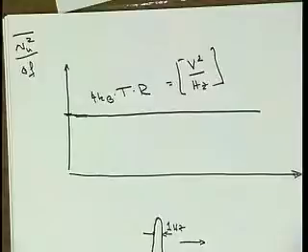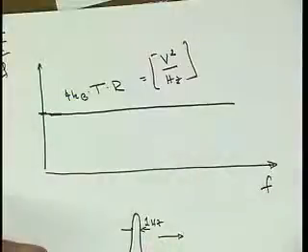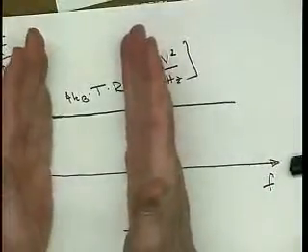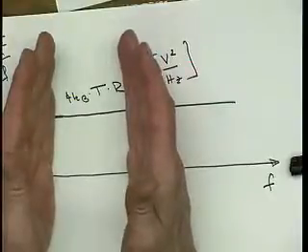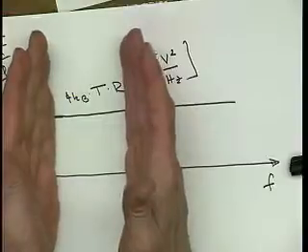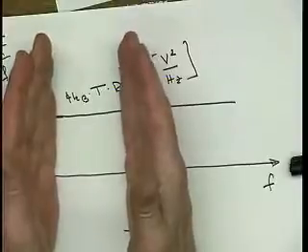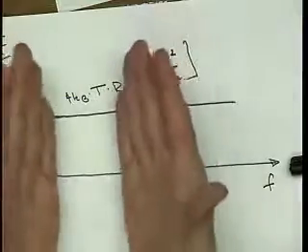Okay, so what I've plotted here is actually correct. This is a function of frequency. For a resistor, for any thermal noise source, the noise is totally independent of frequency. It doesn't matter whether, let's say, we have our ears, which are sensitive from a few hundred hertz up to maybe 15 kilohertz or something like that. All the noise that falls into that band can be detected by our ears, and a small amount of it is going to make some noise. We actually hear that, right?